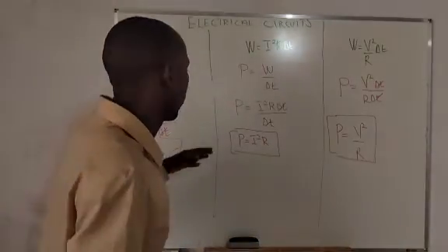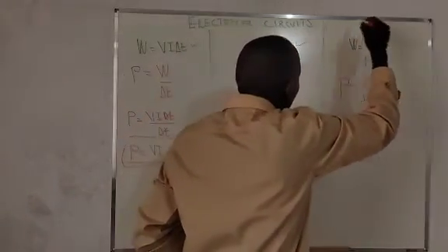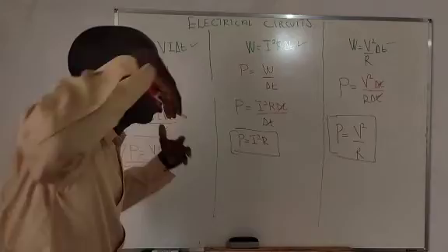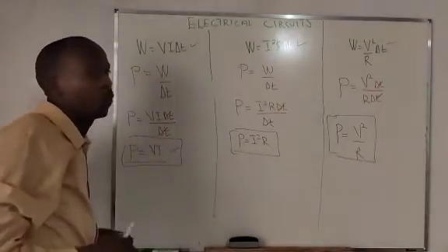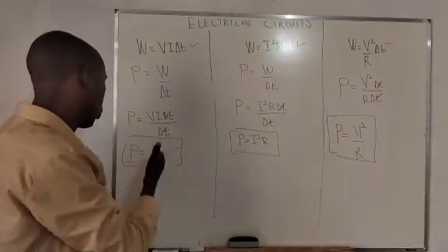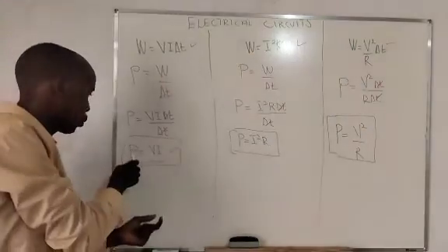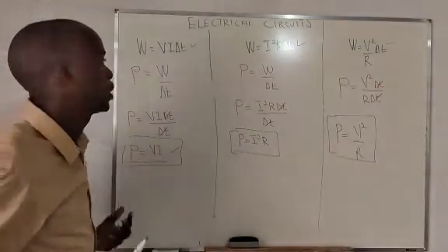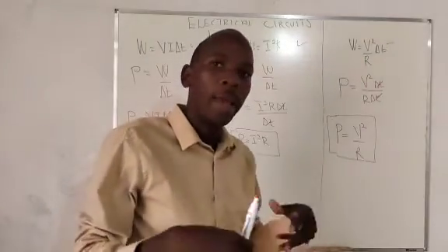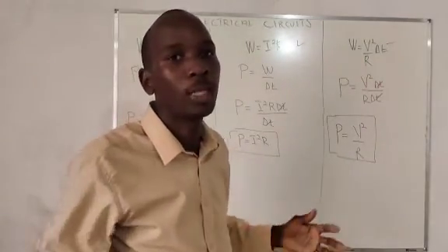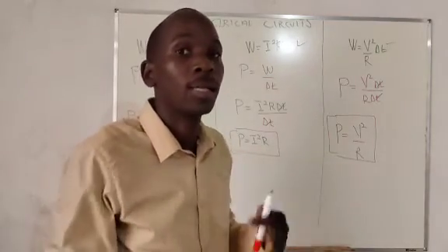As you know, we have to know how to calculate energy dissipated or supplied to an electrical component, and we also have to know how to calculate power. If we know the voltage of an electrical component, and also its current passing through that component, we can calculate its power in watts. So we are going to use every single one of the formulas I have just outlined to solve electrical circuit problems.